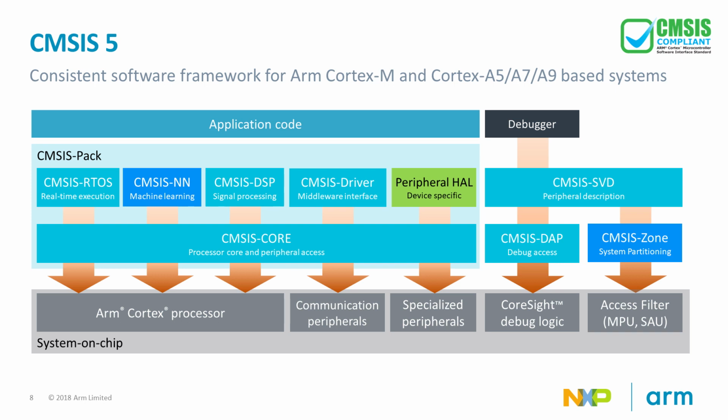First, let's look at CMSIS in general. If you ever did a development on a Cortex-M based microcontroller, you will likely know CMSIS already. If not, imagine CMSIS, the Cortex microcontroller software interface standard, as a collection of standards and software stacks required for a consistent developer story across all Cortex-M MCUs.